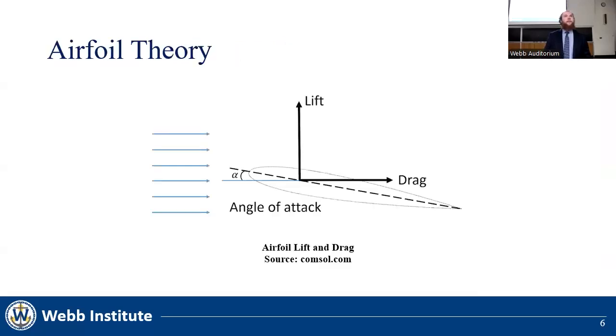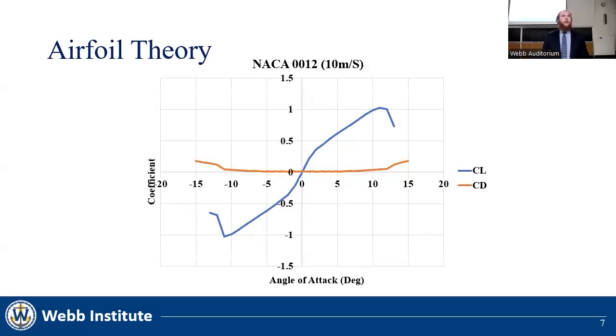Wind tunnels are commonly used for the analysis of airfoils. Airfoils are intended to maximize the lift they create while minimizing their drag. The above graphic is an output from the foil analysis program XFLR5. A NACA 0012 foil was analyzed in this program for illustrative purposes.